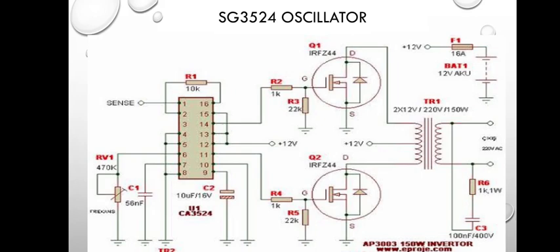Then now the transformer is a center tap 12 volt transformer. Center tap 12 volt transformer. That means from the first side to the middle is 12 volt, and from the middle to the second side is 12 volt. Yes, as you can see.